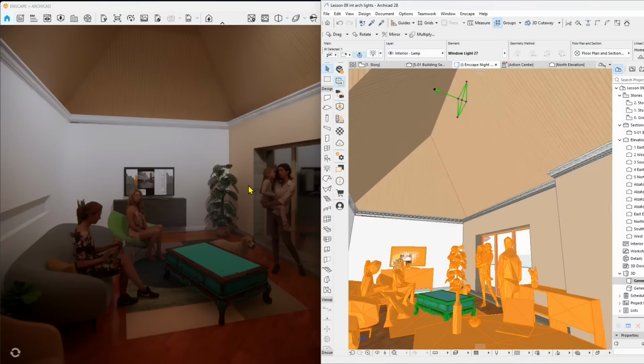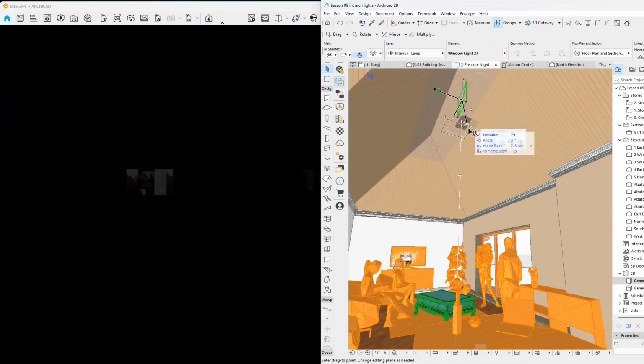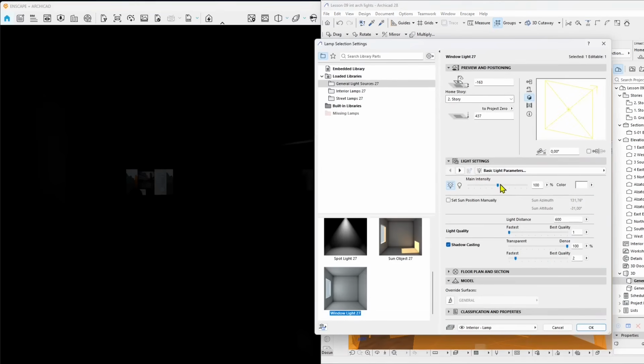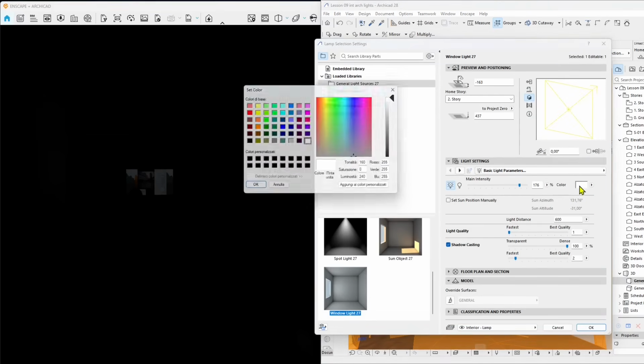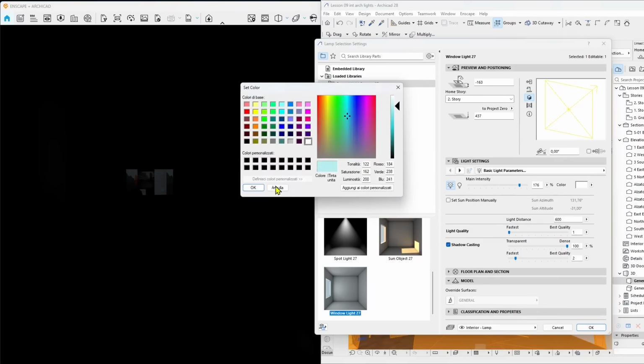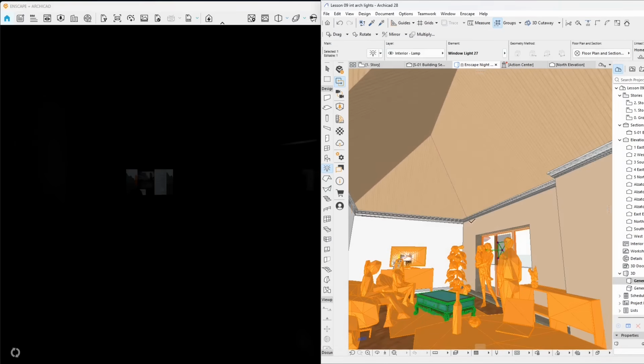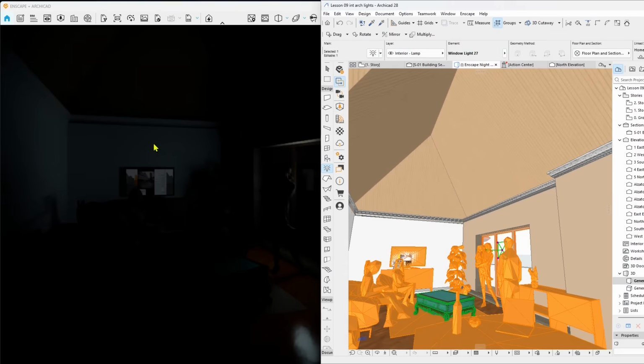Now this also is interesting, it's a portal light. Portal light is essentially a plane light. So you can put it usually next to windows to simulate the light coming from the exterior. So it shouldn't be too strong unless you have like a street lamp or something immediately outside the window. So usually it's bluish, and it should represent the environment light coming into the scene. So something like this will be fine. So be careful, not too high. Or if you want, yes, higher if you're again simulating a street lamp or whatever.